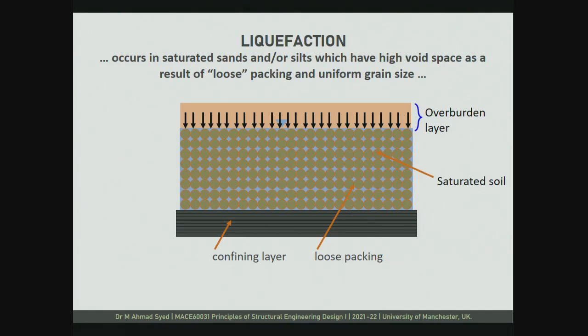So it is also important that to have liquefaction, you need to have a relatively loose soil mass, so that the earthquake can allow the transition to take place, and in that you are letting the pore water pressure go very high.